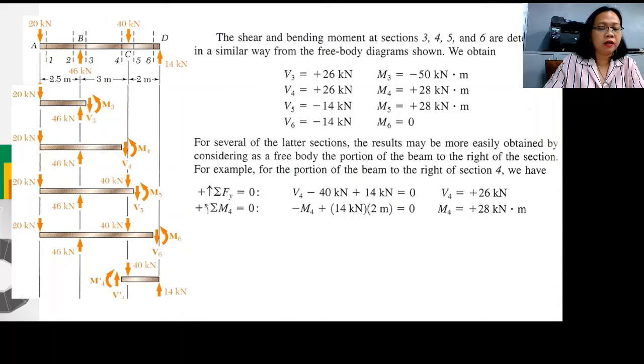Okay, you following? So we have shear and moment. Since our convention is that if our beam is to the left, then our assumption is that the positive shear is going down, and our moment is counterclockwise. Okay, let's see if our assumption is correct.